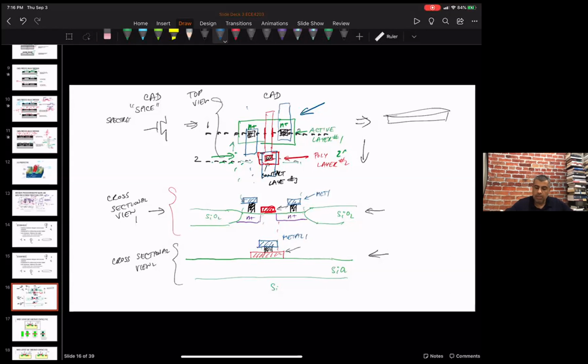For example, a CMOS inverter, which we'll talk about later today. It's an inverter, right? That looks like a PMOS connecting to an NMOS with the NMOS source grounded and the PMOS source connected to a high voltage. That's called VDD. Let's say that's whatever it is, depends on the process.